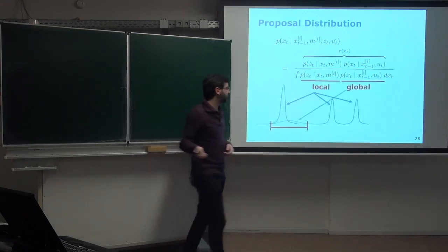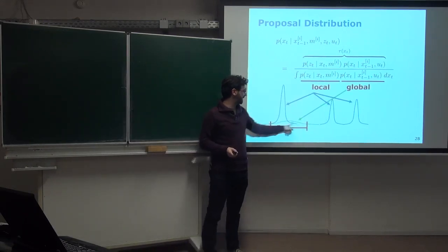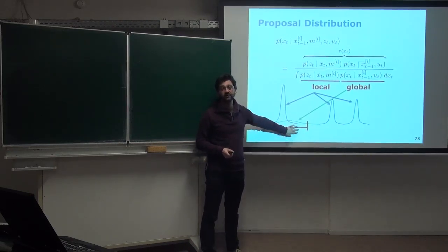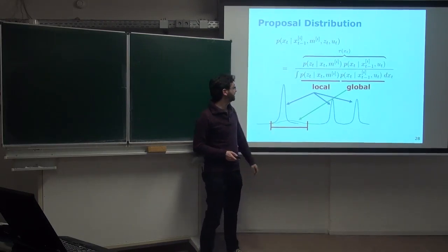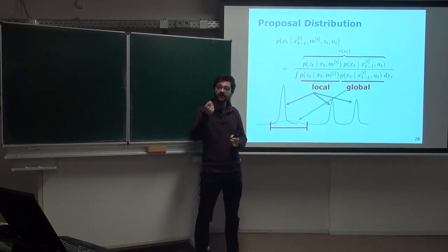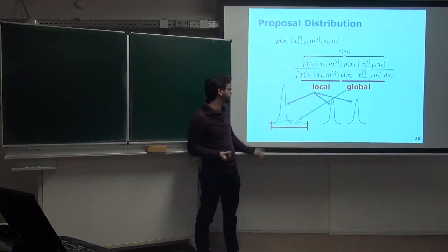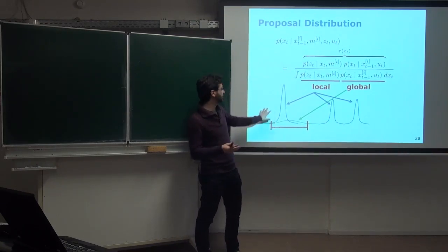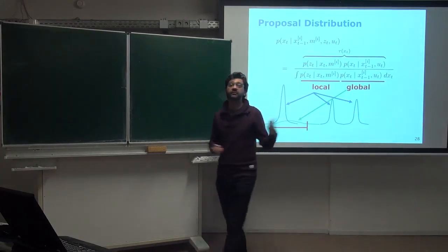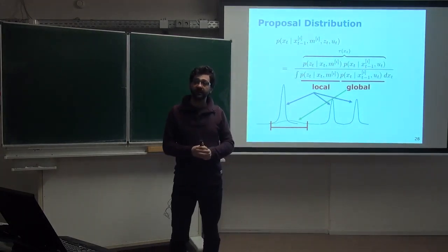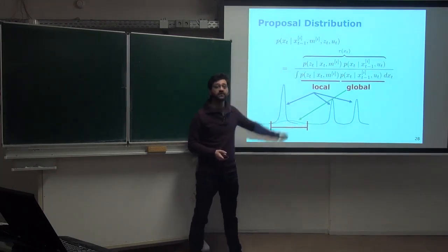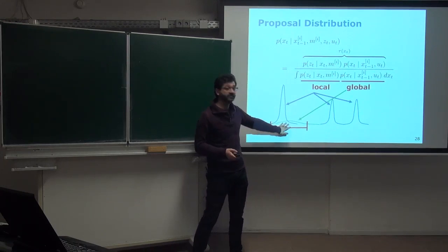So if you see it graphically, it's our odometry that somehow blocks us globally, because that's the only place according to the odometry where I can be. But then if you consider just the likelihood, and we try to see which is the most likely place I have given this observation, if the environment is kind of repetitive, we can have some peak distribution here, but also some other peaks somewhere else that look like the place where the robot is at this moment, okay? But since we can limit ourselves with this, what we can do is just try to be around this part here.